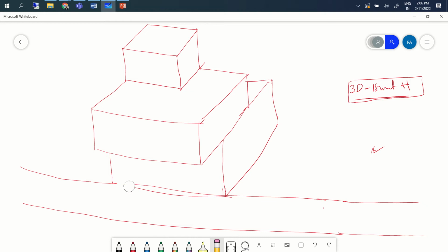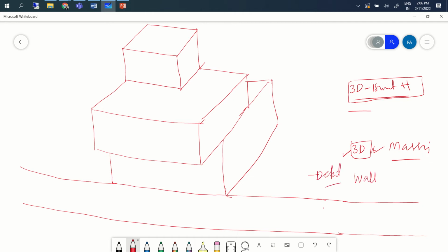Anyway, fine. Let's see, I can make a little bit more clean drawing. Okay. Now, initially what I said is you should make the massing. This is called massing, where all the three-dimensional volume of the building that you are trying to do is done in an isometric drawing. Later I said maybe you can add walls. I said do the detailing. When we say do the detailing, we should show, let's say, windows, any projections. I'll write here windows or projections, or let's say wall thickness, and so on and so forth.